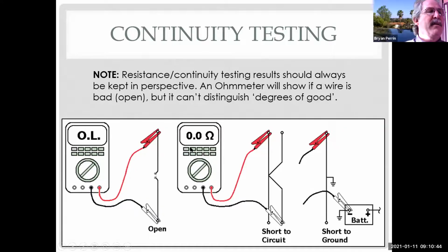And so this is why we don't just use an ohm meter to find out if a wire is shorted to ground, because it's going to go back through all the different loads. And since the series are open, it's going to come out and say, hey, we're shorted, even though we're really not. And that's why we have to isolate and test one piece at a time with an ohm meter, which is why we just don't do it anymore. We use voltage drop testing for it, or we use current to see if we need to use voltage drop testing.